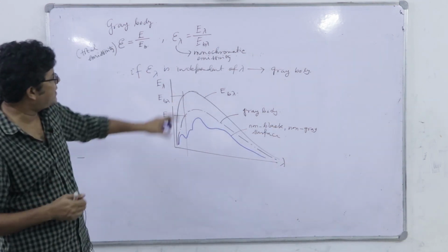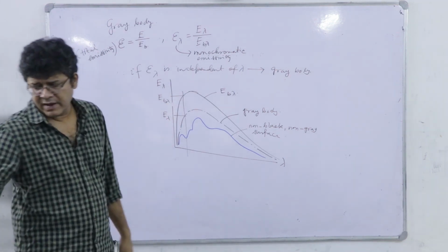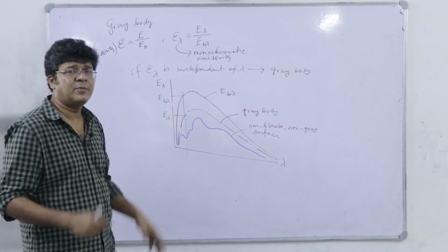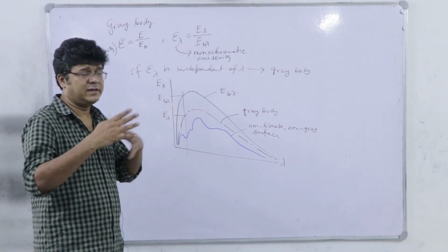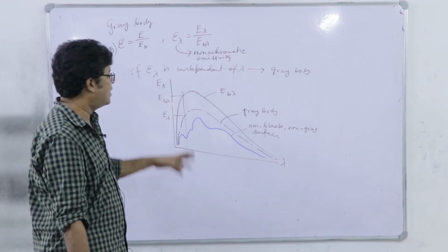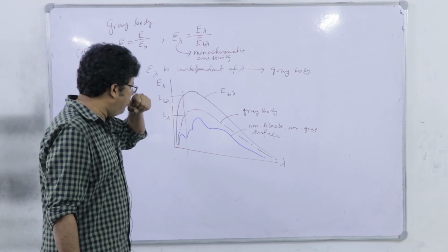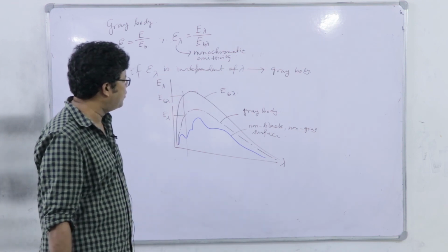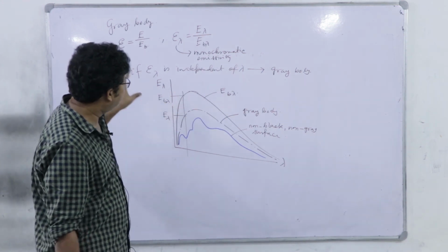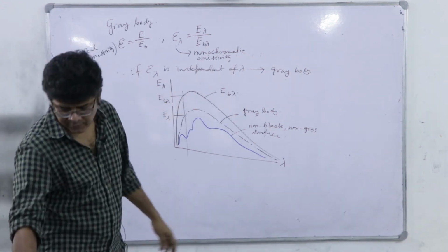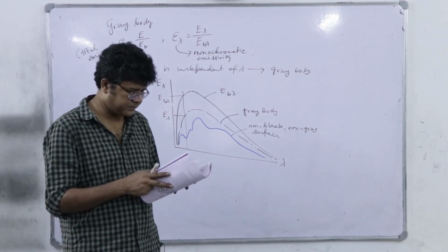Gray body at least we will use this idea because many industrial surfaces can be well approximated by a diffuse gray surface. Diffuse means where there is no spectral preference of emission, right. We will discuss it. So, that type of surface we will call a gray surface, and with respect to that we have defined a gray body and the respective monochromatic emissivity term, right.